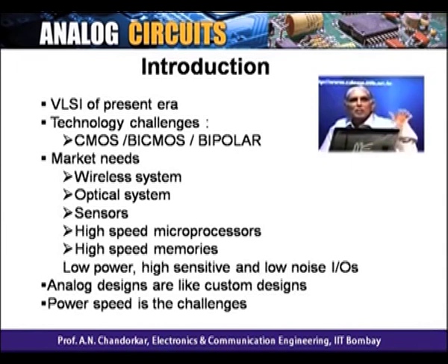So I'll go for 22 nanometers, maybe a 16 nanometer process. But analog says if it is 1 micron, I am very happy. The larger, the better for me. Now that means you are trying to put an analog design on a digital technology which is worse for it, and now you expect that it should behave far superior. It's asking too much.